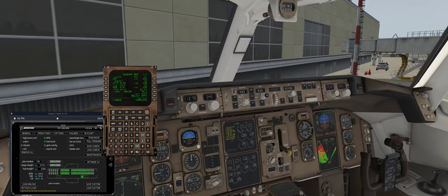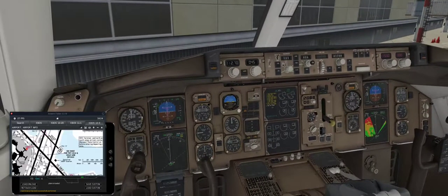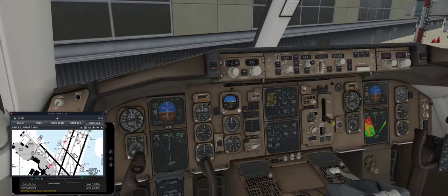Our runway, we'll keep our attention here. And actually, we're done there. Legs is empty. We'll come back to that. 15 right has a heading of actually 150, which is nice. It doesn't always match exactly the runway name, so you always look at the charts. And we're going to cruise at, what did I say, 25,000.